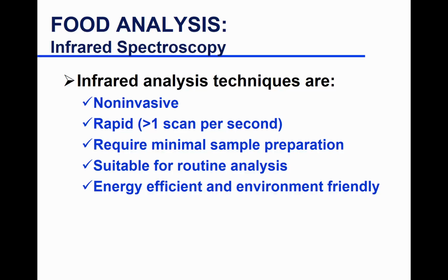So for example, those of you that are working on your projects already and trying to identify tests during processing, if some of the tests are, let's say, quick tests for moisture, or solids, or fat, oftentimes it's the IR, not the lengthy oven methods or the lengthy fat analysis methods. It's energy efficient and environmentally friendly. You don't need reagents. You don't have any bad outputs that come out of that instrument.